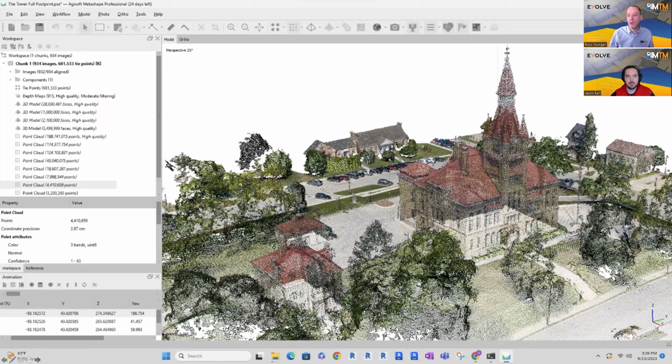Again, with that laser scan data from here, you'd have a lot of gaps on the roof because there are no adjacent areas that you can scan from, a lot of holes here. But essentially, you'd have the entire side of the building and many of these higher features that you can align directly to and get a much more dependable aligned deliverable there.